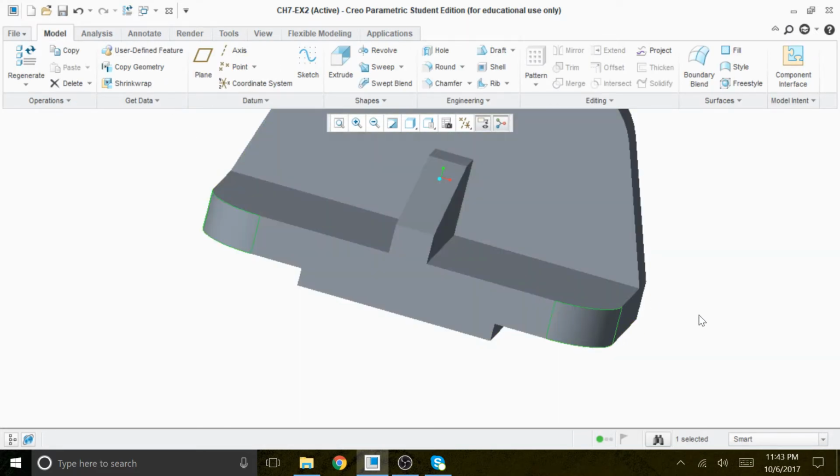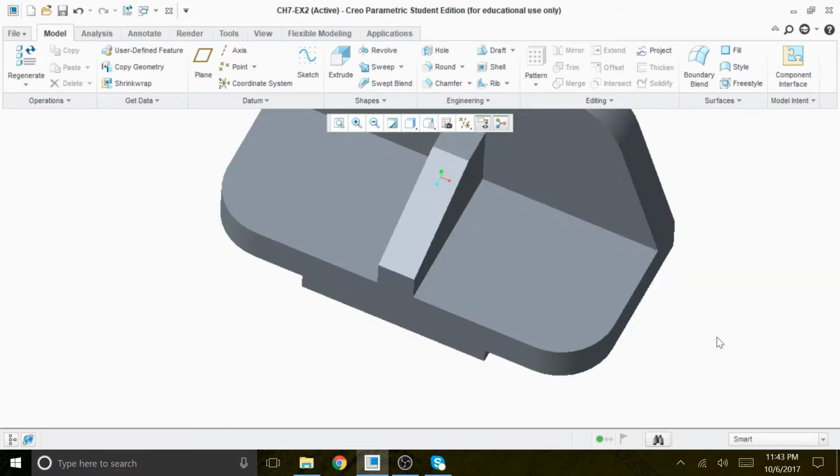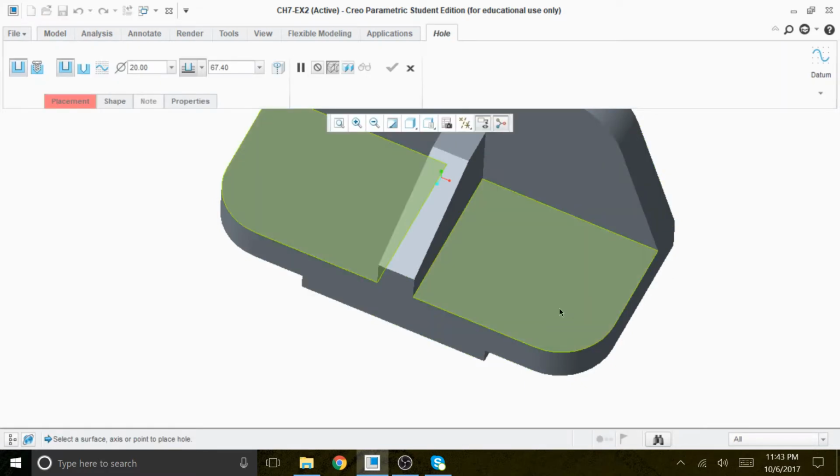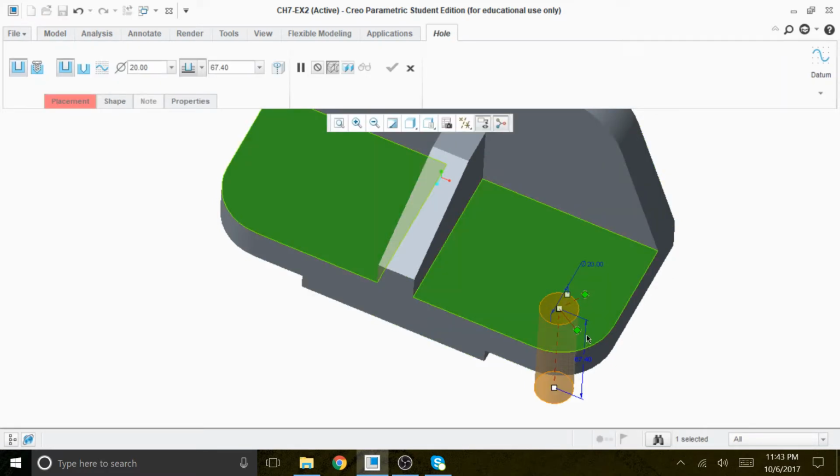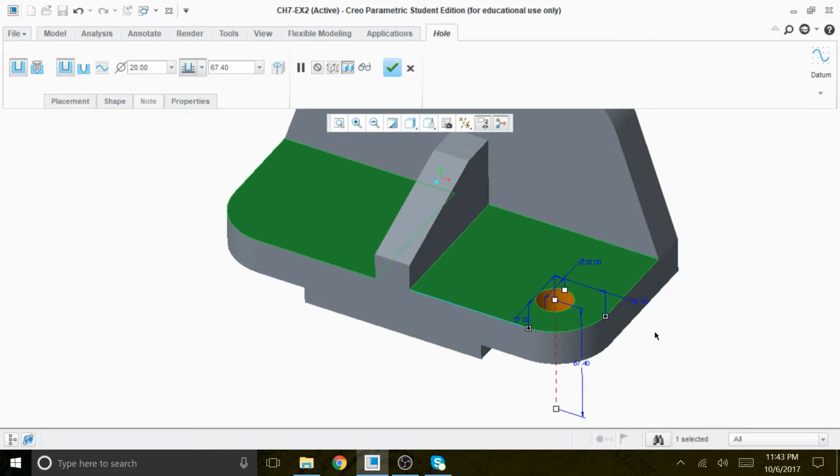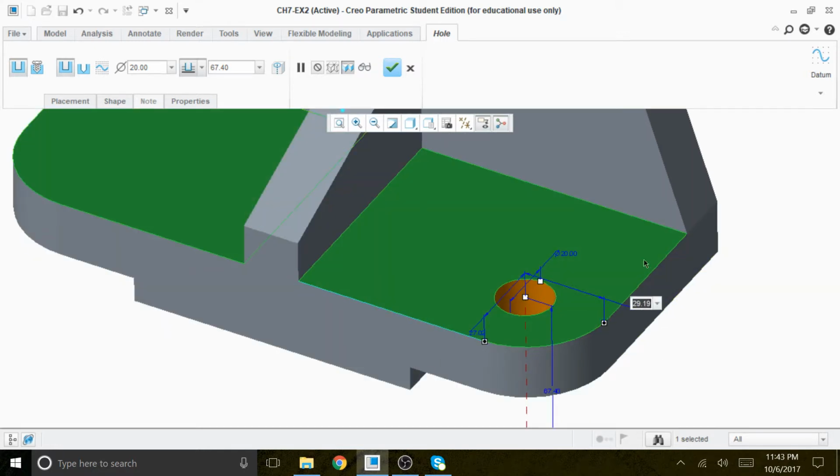Okay, all right. So next we're going to do the counterbore. We're going to create a counterbore on the top. All right. So we're going to go to Hole Tools. I'm going to drop it somewhere here, and the measurement with respect to this edge and this edge should be 30 by 30. Okay. So I'm going to put this against this edge, and this against this edge. There's two handles, and if you zoom in you can see that should be 30. Enter, and this is also 30.